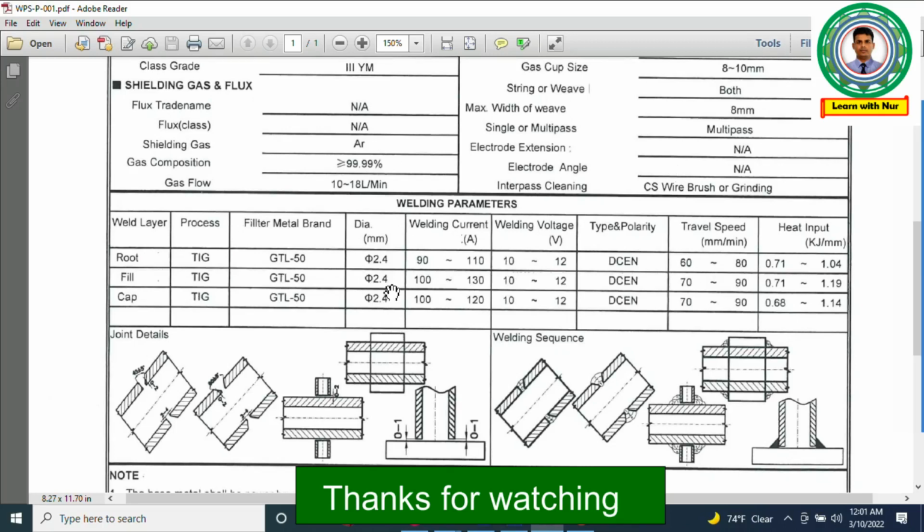When we get the welding current, voltage and travel speed, by these three we can calculate the heat input. So we have to keep the record during welding: what current they are using, how much current they use, the voltage, and what the travel speed is.